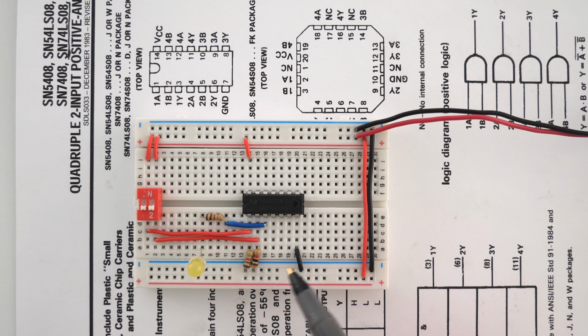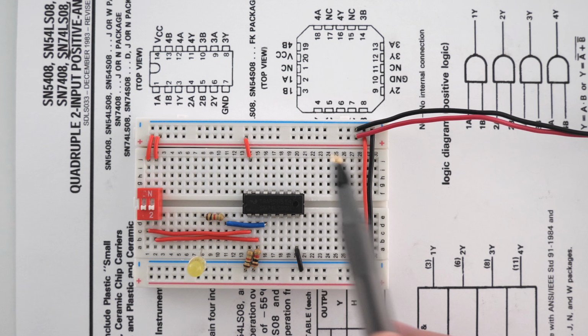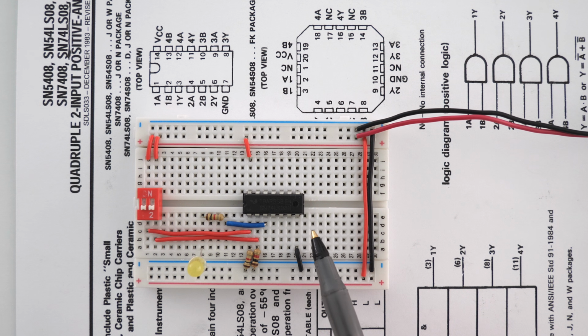Now you'll notice that we had to add these two resistors here into ground, because if we didn't add these resistors, whenever this switch was turned off, these would be floating and they would still be interpreted as an on to the integrated circuit because of that pull-up resistor. So if you add these two resistors to ground and you have your inputs coming from the positive 5 volts, this circuit works exactly how you would expect. And this is the way I would recommend wiring up these integrated circuits.